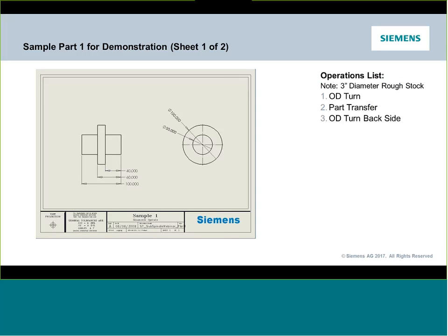We'll turn it from 100mm diameter down to 50mm, and each of those steps only goes 40mm back, so there's a 20mm gap in between the steps, keeping my part 100. I'm not going to worry about facing, and we're not going to put any fancy grooves in. This is quick, simple, down and dirty to get you to understand this transfer process.